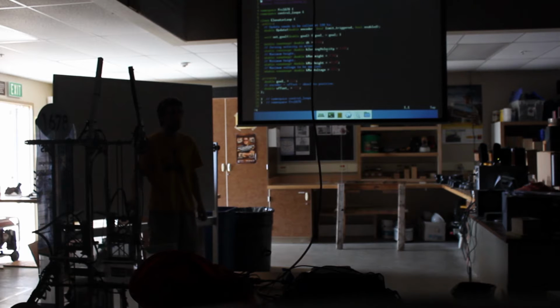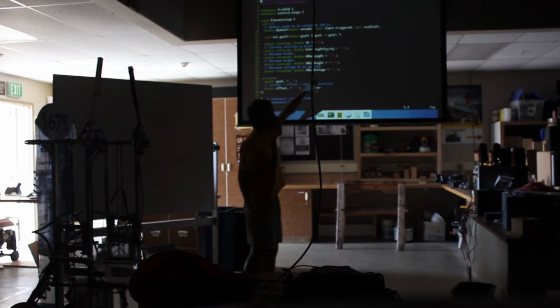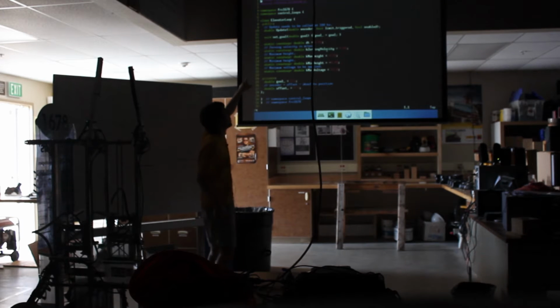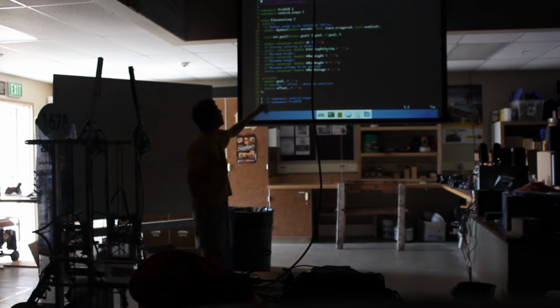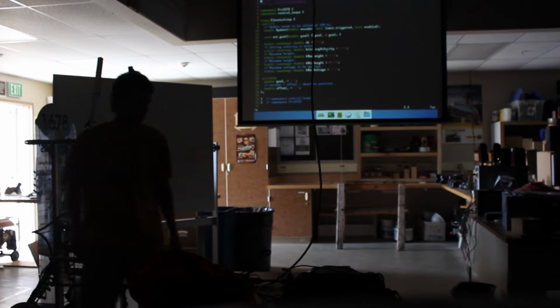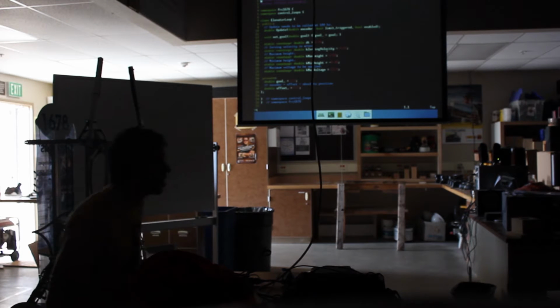We're going to call this position 0. We need to define a coordinate system, so 0 is when the elevator is at the Hall effect sensor. And then it's going to take an enabled bit, so something from the field saying the robot's on or not. And then it's going to return a voltage, saying this is the voltage to command the motor. So it's a pretty straightforward interface, which we can implement a quick simulation for.